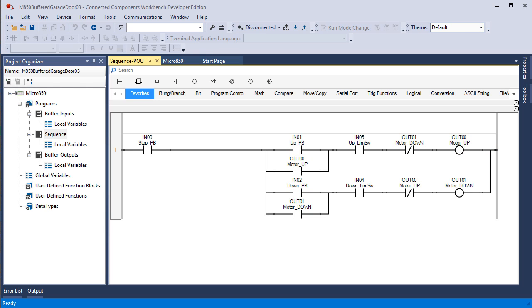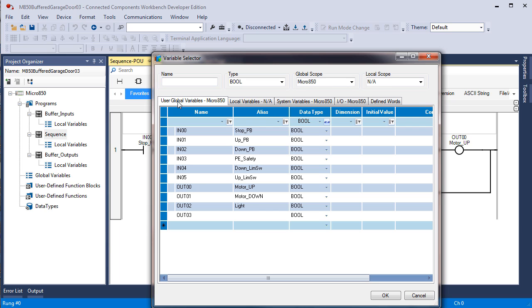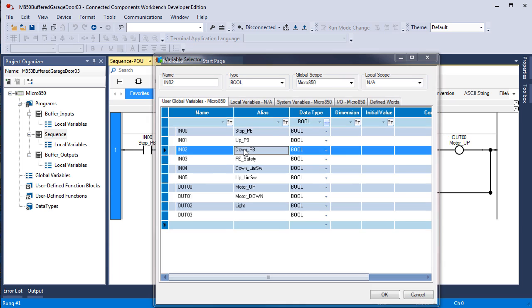We wanted to explore some ideas, modifications to the logic that could improve the situation with operators with wandering hands working the push buttons to see what they can cause that's different. First thing that we did was we added logic to each push button to disable the push button if the other push button is pushed. That's real simple. We go here, drop in a true if off, and that was the up push button, so we go to the down push button.